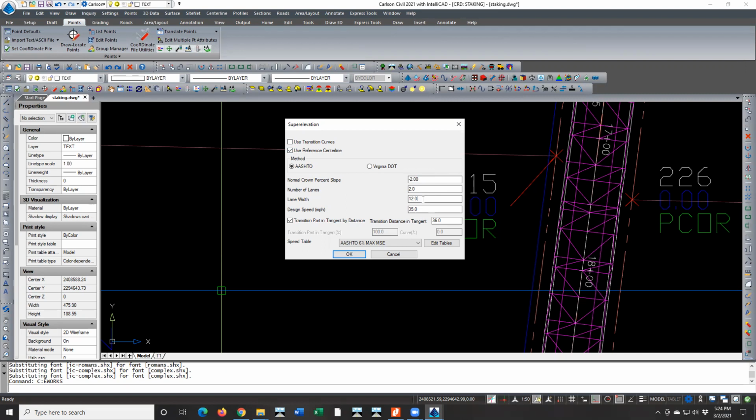So yeah. Now here's going to be an issue. Say I've got a 12-foot lane. That's fine. How's that going to affect our template? It's not up there with those 12-foot lanes. It's got that 20-foot subgrade width, but we could do 20, and actually I'd rather do 20. I think that's what I originally had in there at some point. All right, so we'll do that transition part.